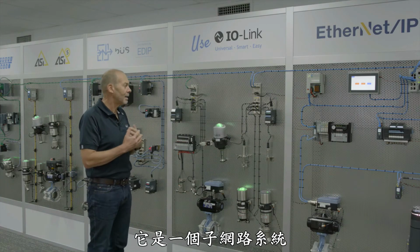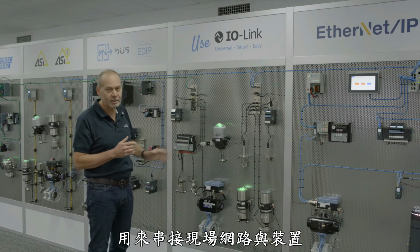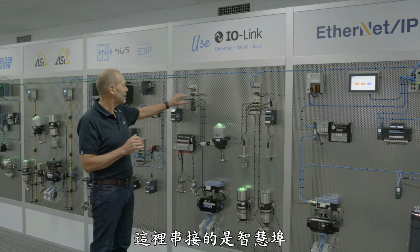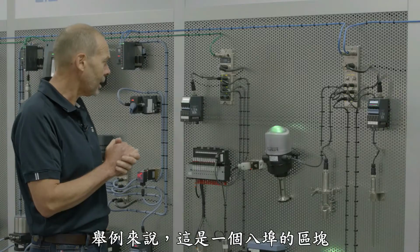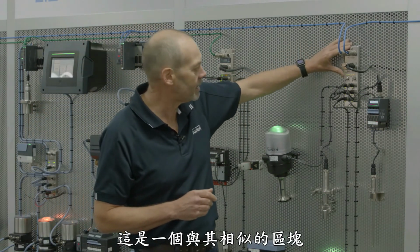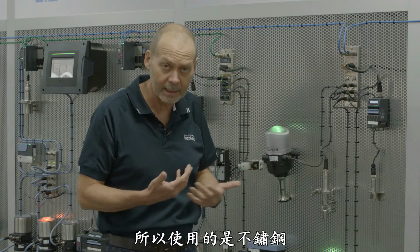So it's a sub-network where we actually link these field networks to individual devices, but not like an I/O block where they just link to simple devices. These are smart ports where they can actually link to digital devices. So to give you an example, this is a block of 8 for a standard industrial application, and this is a similar one but used in a hygienic application, so therefore in stainless steel.